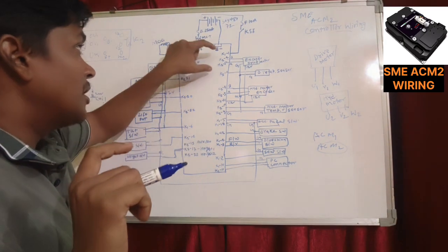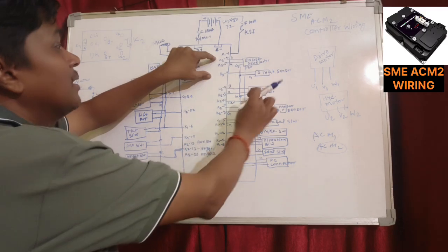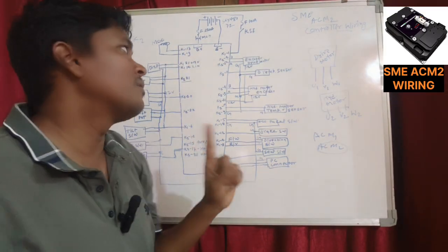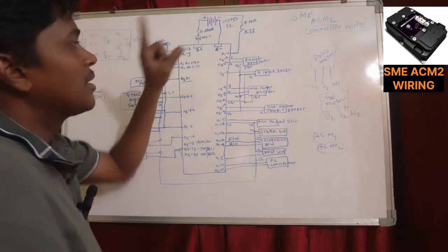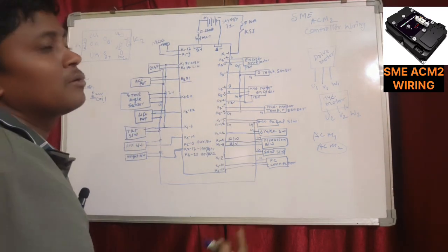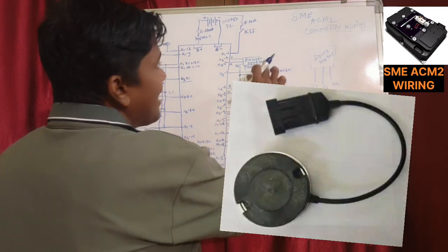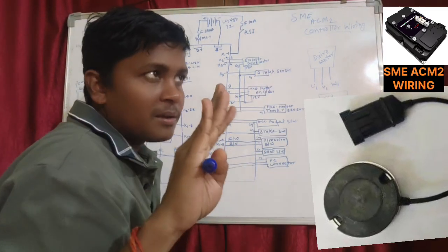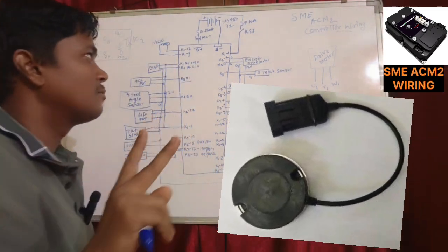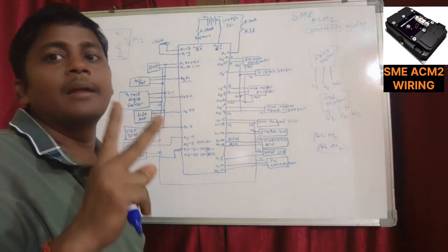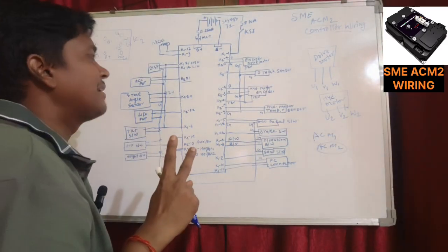See, this will be compulsory. If you connect the hydraulic motor's encoder connection to the drive motor, the controller will not work. It is compulsory to connect the drive motor encoder connection only with the drive motor encoder. See, the drive motor encoder has 4 points. This controller operates a 2 channel encoder, channel A and channel B, not a 1 channel encoder.